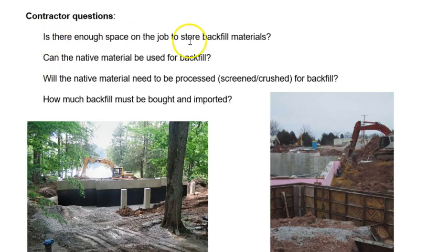Is there enough space on the job site to store backfill materials? So we take out the earth materials, then we build the structure, and then we need to backfill. Is there room? Large sites usually do have such room, but tighter urban sites, obviously not.